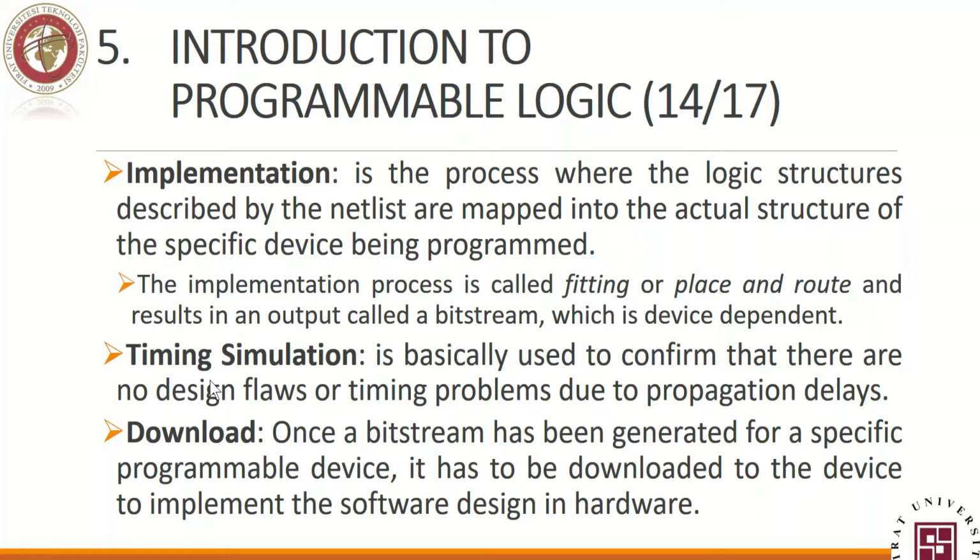Why timing? Because we may have a problem with the propagation delay. We think of our devices, our gates, our components, as maybe ideal or with no delay, but when we try to test them practically, we find some delay, so we need to make a timing simulation and see if there is any delay or not. If there is no delay, then that means our software is ready to be downloaded to the hardware, the device that we have.